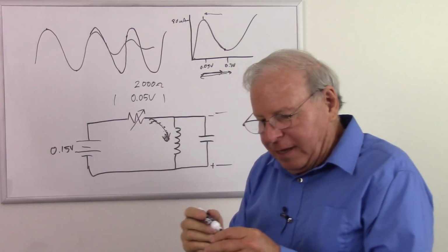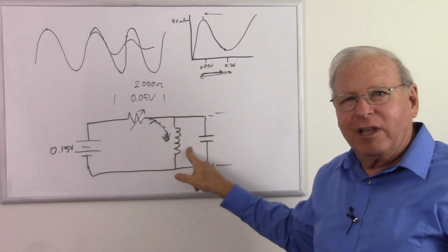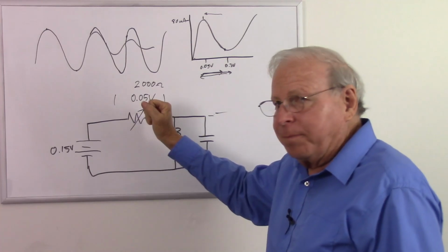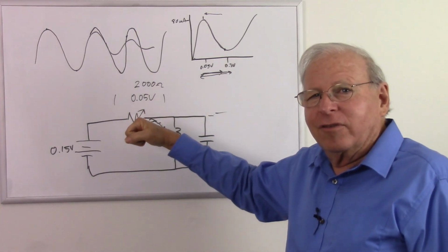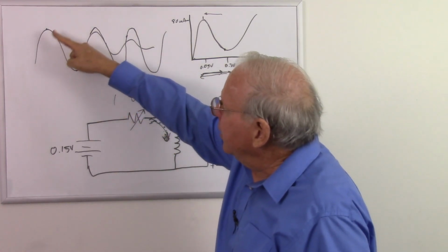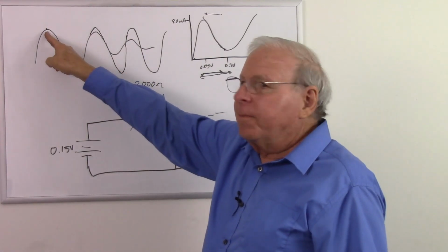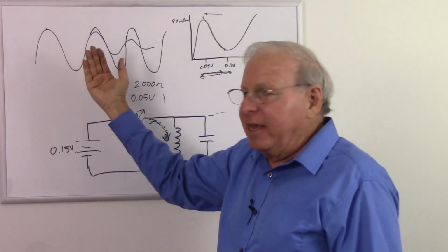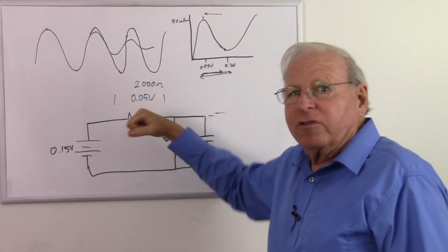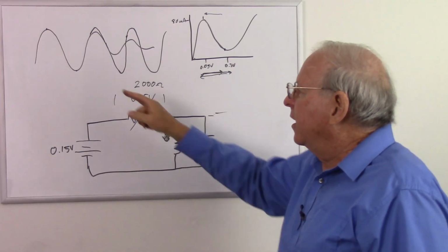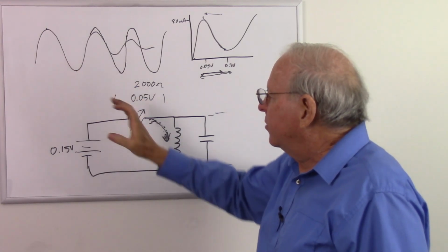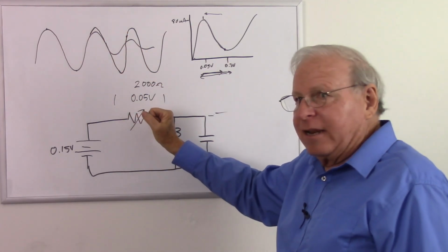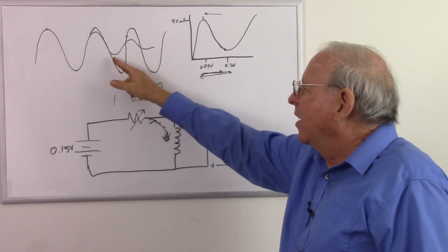So actually, the sine wave generator using the tank circuit here is even easier to analyze than the relaxation oscillator, because this is simply changing its impedance going up and down, following this curve such that when we are up here, its impedance is low, pushing more current in, forcing that to go up and keeping the energy in. But when it goes down, the impedance goes up, meaning less current going in, allowing this to drop back down. As it goes up, impedance goes down, more current in, pushes it up. As this drops down, the impedance goes up, meaning less current, allowing that to drop again.